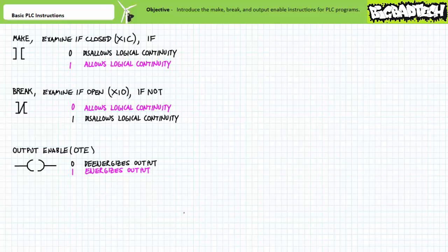Loads hooked to a PLC output include the coils of contactors, the solenoids of fluid power valves, and indicators like LEDs. Normally, a PLC delivers output signals via an electromechanical relay for AC or DC loads, a solid-state transistor exclusively for DC loads, or a triac or back-to-back reverse parallel SCR exclusively for AC loads. Let's assume we're dealing with electromechanical relay outputs since they're the easiest to understand. We'll discuss the peculiarities of the solid-state devices in other lectures.